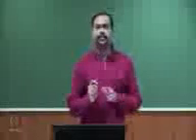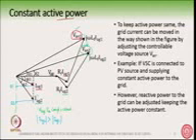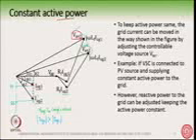So this is possible by adjusting the controllable voltage source, because the voltage source converter is a controllable voltage source. So I can place it as per my wish. I can lag it, I can lead it, I can increase the magnitude to the extent which is possible by the converter. So this is what is meant here.